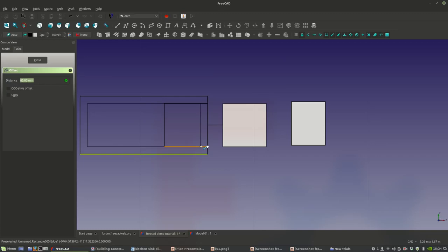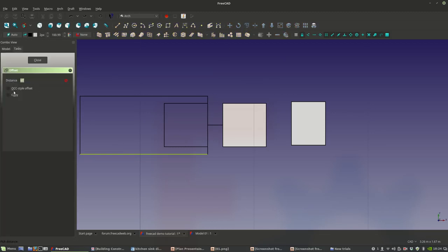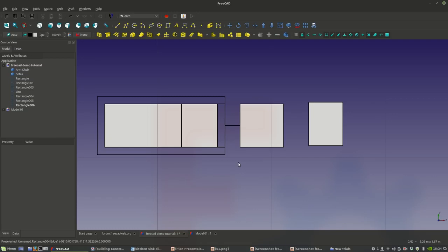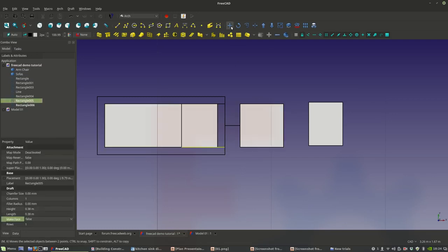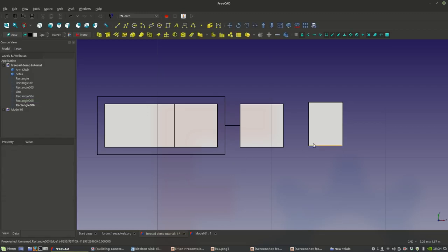Okay, that seems to work just fine, and I didn't get the copy tool, so offset and copy right here. Alright, looks good. So now I can just take this guy and move him once again, undo the copy, and just move him onto the side here like this, and there you go.